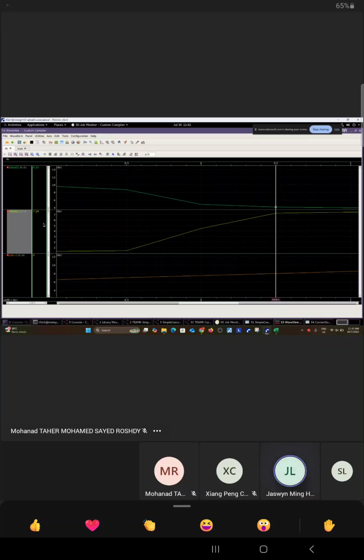Maybe the only bad thing is the gain somewhat gets smaller. I think the output swing gets smaller, but the effect seems very minimal though. It decreased by 0.4 volt. Maybe there can be other issues because just now we did not only change the tail current, right? We also changed the width of the top MOSFET.